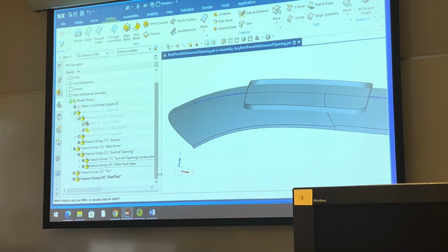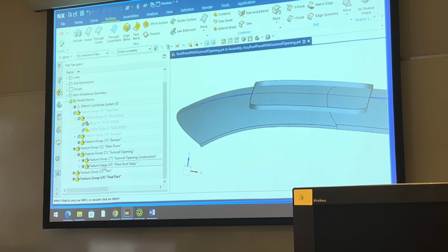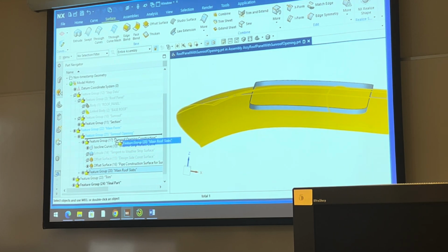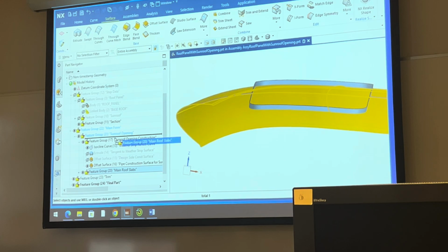And I just like to talk about this because it's easy to forget this. You can drag it sometimes, but when I go to drag it, see that little black line, remember this? I see you keep jumping ahead there. That little black line right there, there's a subtle difference. Right now, if you look at that black line, it stops under the word feature and feature group right above it, right? See the blue feature group, 21? It stops right by the F. If I slightly move my cursor, now it's stopping left of the folder. See that? If I slightly move this again, that black line, now it's to the right of the folder. Now it's under the folder. That makes a big difference.